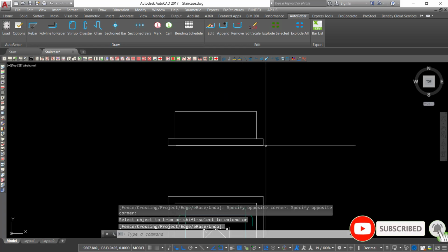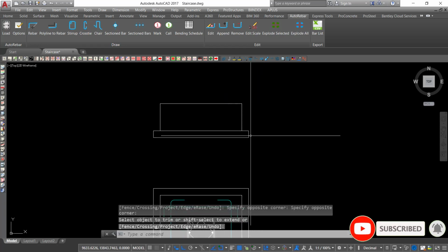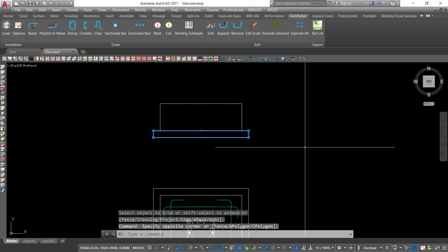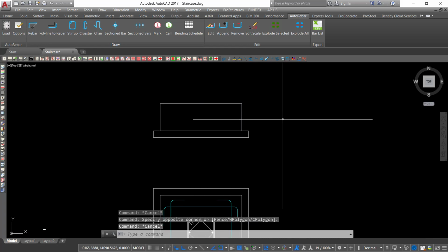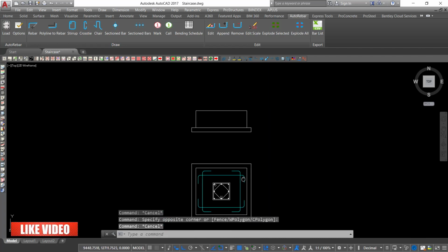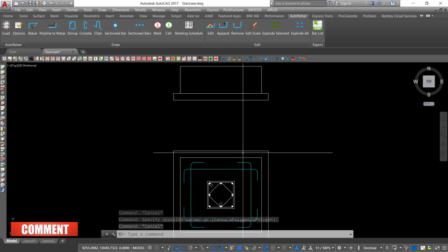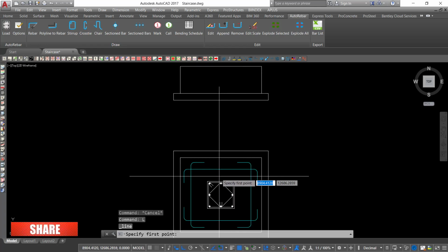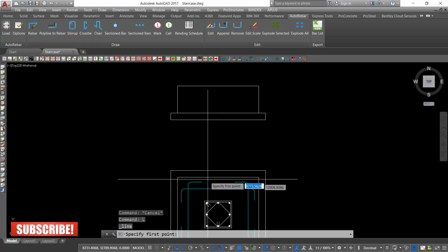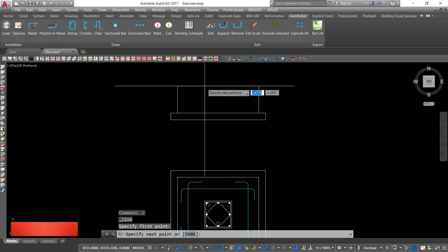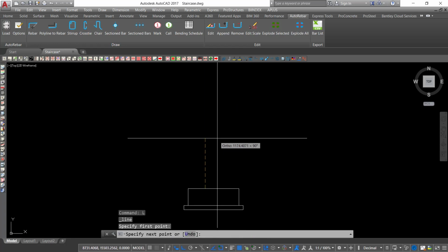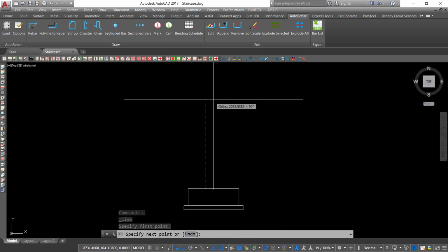Right click and enter. So that's how you can do it. So we have the blinding in place and we have the column base already coming up. Now let's go to the column itself. Now we have the column right at the center here. I'll type L on my keyboard and try to mouse over this and move all the way to the top here. Now allow my column to stretch all the way by 4 meters high.